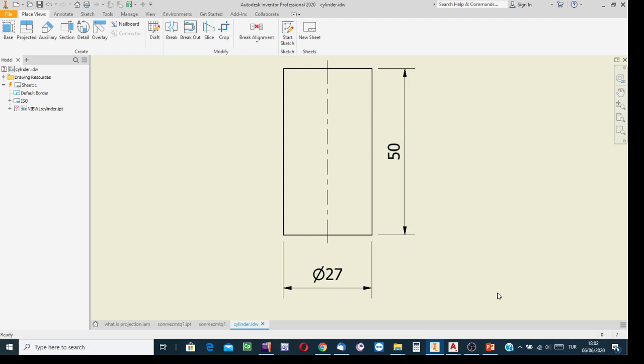In first quadrant projection, if the dimensions have been shown not in millimeter but in centimeter, then since it is contrary to the common convention, the unit of measurement is to be written at a certain part, preferably at the title block of the technical drawing sheet, saying that dimensions are all in centimeter, for instance.